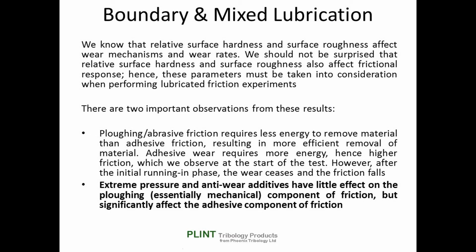We know that relative surface hardness and surface roughness affect wear mechanisms and wear rates. We should not be surprised that relative surface hardness and surface roughness also affect frictional response. Hence, these parameters must be taken into consideration when performing a lubricated friction experiment.